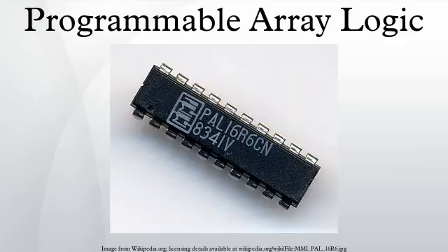device. PALASM. The PALASM language was used to express Boolean equations for the output pins in a text file which was then converted to the fuse map file for the programming system using a vendor-supplied program. Later the option of translation from schematics became common, and later still, fuse maps could be synthesized from an HDL